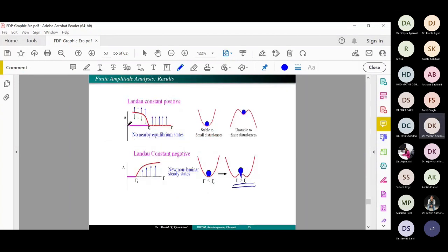This point is the linear stability critical point. Beyond that point, the flow is going to be unstable. The dotted line is the unstable branch, and two stable branches are there. That is called a subcritical bifurcation. And subcritical bifurcation is the most dangerous bifurcation in fluid mechanics, because it shows that the flow at the linear stability analysis point is not in a stable situation. At a linear stability critical point it is not stable. We need further analysis for the bifurcation analysis.